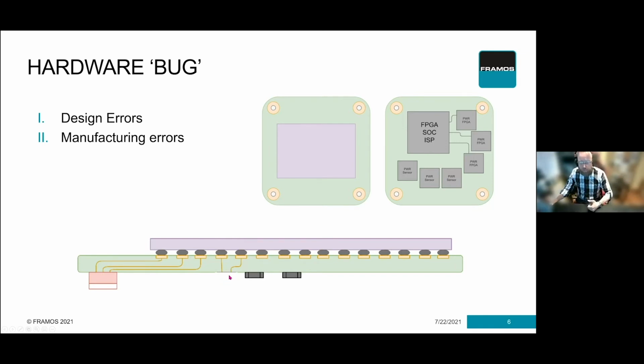So, for example, removing this or forgetting to have this populated, either by the CM or something, the absence of this device could make the system not work. This could be a critical piece, for example, the analog power supply that actually provides the power to reset each pixel. It could be along the same lines, but it could just affect the noise. So the whole system works perfectly, except the images just don't look as good as your prototype or as good as the evaluation kit that you originally had in place.